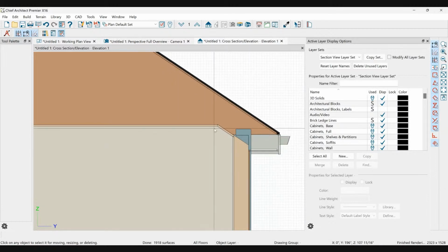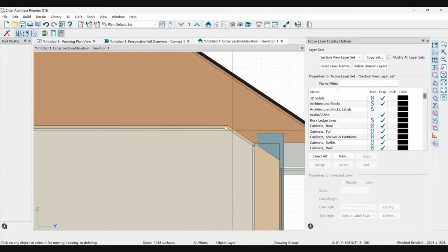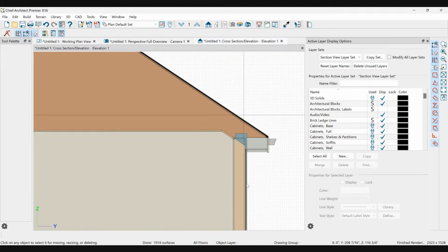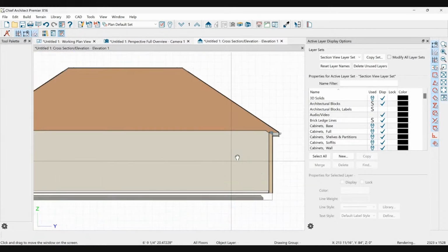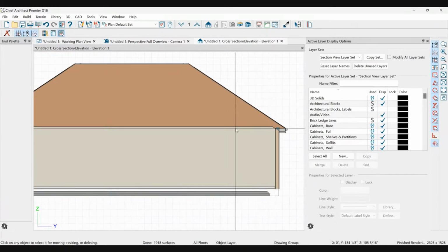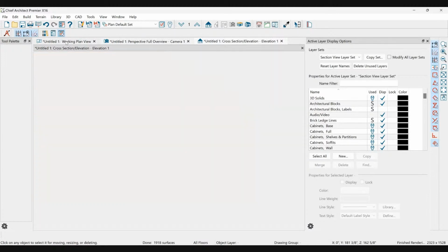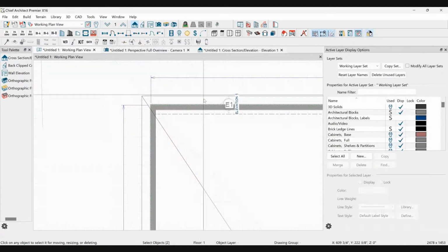Now, if all my flat ceilings were 9 feet, I have this little chunk of rafter that's like now part of my room because I pushed the roof plane down into the room. So you could get around that by lowering the ceiling height in your room, like furring it down or something, or all kinds of other things you could do. But it's just not a good idea. That's not a good thing to prioritize.